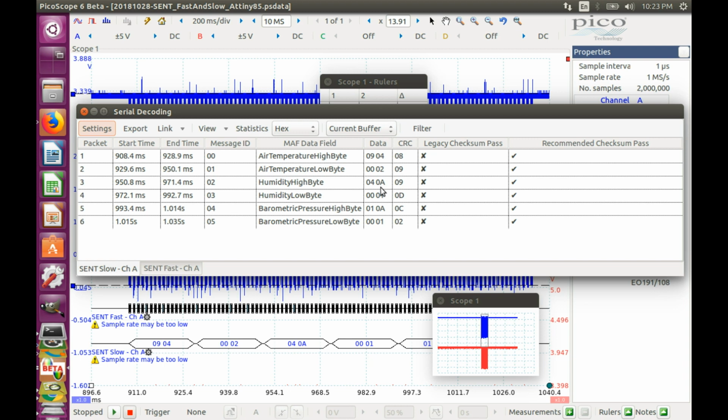And how is it getting this voltage? It has an internal reference, 1.1 volts, and it sends it to the ADC channel that receives power supply from approximately 3.3 volts in our case, and the digital result is being reported here as 330 out of a total 1023.